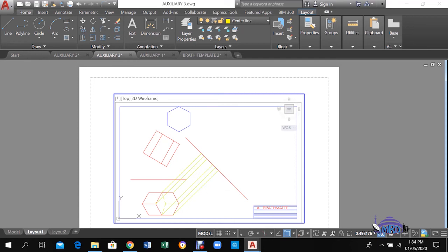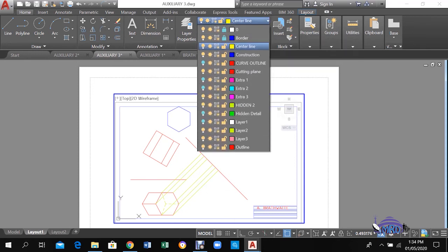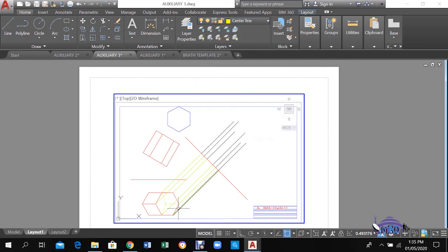Once we have those in, then we move to our next stage, which will allow us to mark off the heights. Remember that each of these corners comes from up here. So now the height will be transferred to the corresponding line going across here. So this first corner here will come up. That's this first corner marked here that's highlighted. And the height for that will be from the XY line to the top corner on the drawing. And then that is transferred here. And you do that for every single corner that you plot.